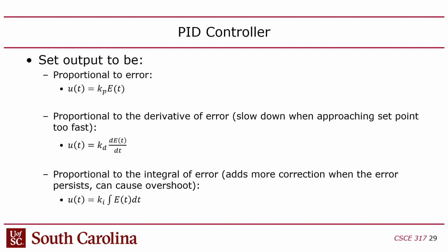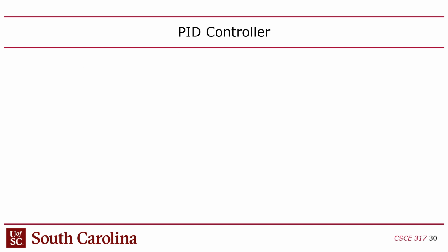But I don't think they covered any of the background of why this works, right? So basically, you have 3 tuning variables. You have a coefficient for the proportional control, a coefficient for the derivative, and the coefficient of the integral, right? And so basically, you choose these, and you get a differential equation that looks like this. You have the error term.